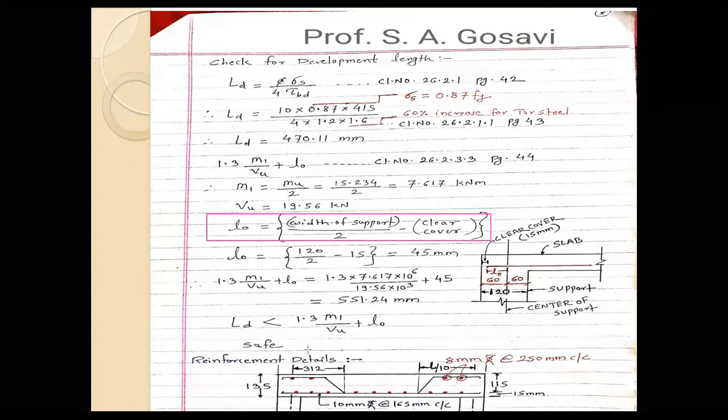For the distribution steel, you will not see the length of the bar, you will see the dots. Okay, so the diameter of the bar, that is the cross section. So this is the bar of main steel, 10 mm diameter, about 165 mm center to center. So this is the main bar. It starts from this point. This is the bar profile. Observe it carefully.